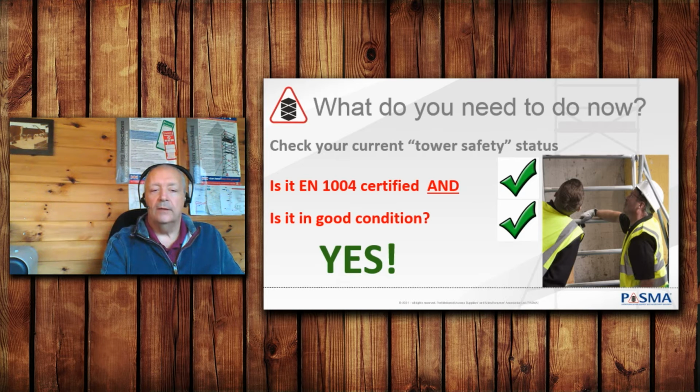But when it's worn out or damaged and needs replacing, or if you need to buy additional towers, then you should only buy a tower that complies with the latest EN 1004 Part 1 2020.